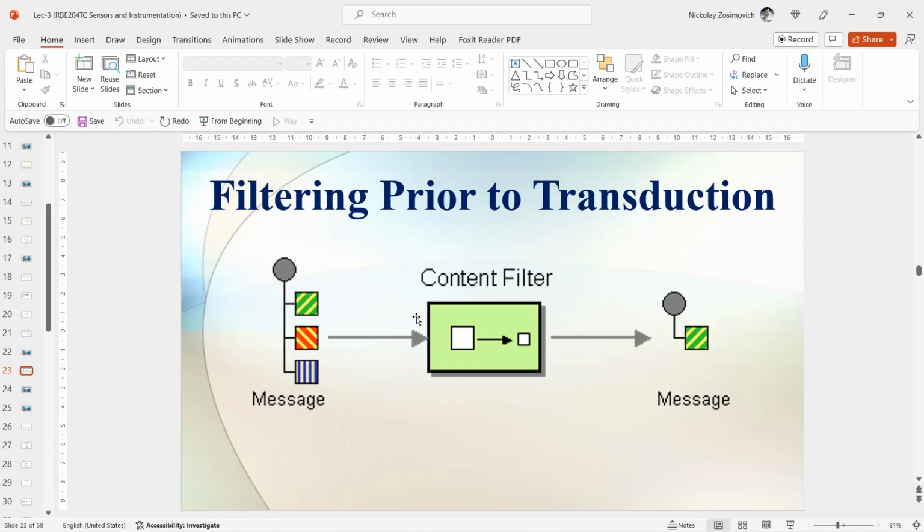Third is the changes in environmental temperature, reduced by thermal shielding and encapsulation with high thermal resistance, or a temperature-controlled housing, which reduce thermal effects. Fourth, unwanted optical input from lamps, the sun, and so on. All of that can be stopped by optical filters.